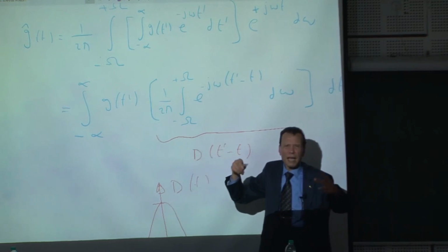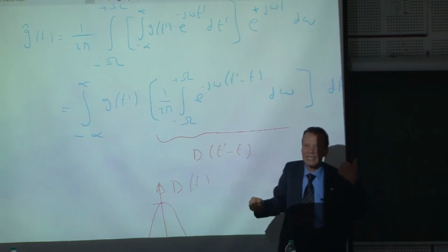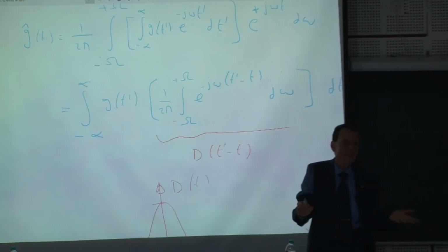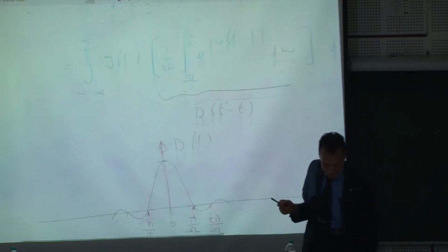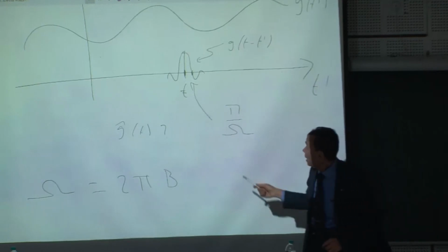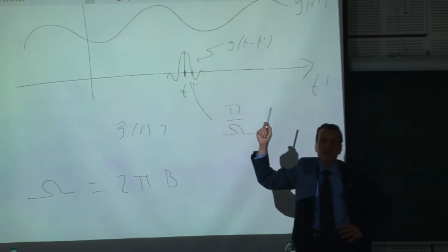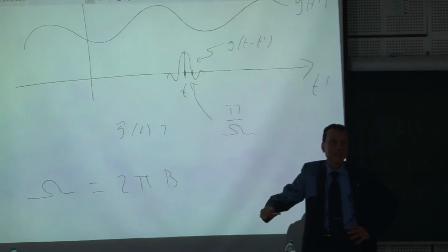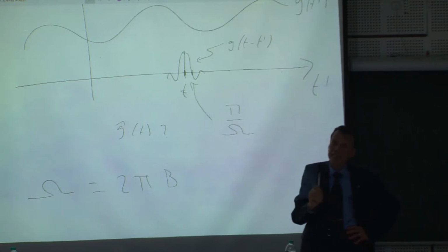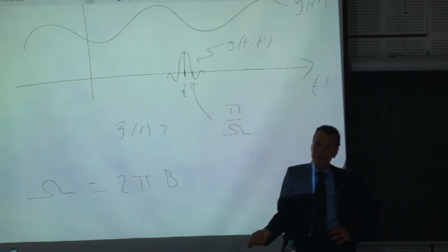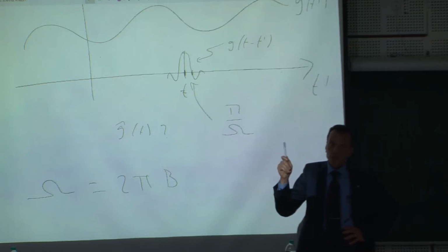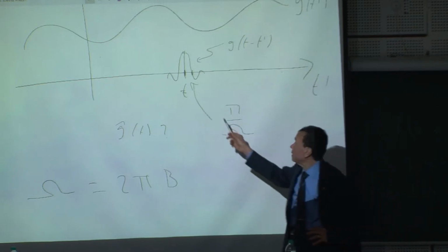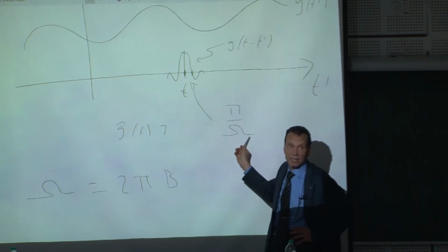Of course, you know Hamming, Hanning, and so on for the discrete case. But what happens in the discrete and the continuous is the same. But as you see here, I will have the advantage of lowering the artifact. I pay with something. So as you see here, as long as I keep the measurement bandwidth the same, and I would like to improve something, I must pay with something else. So here, in order to raise the resolution, you may increase this one here.